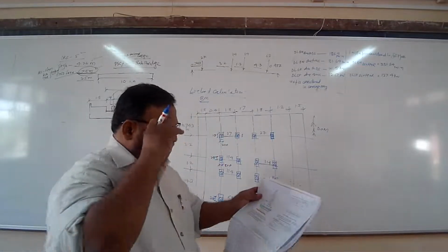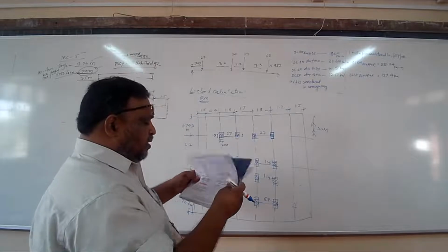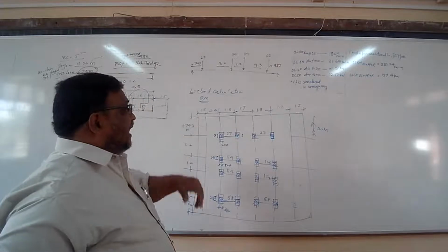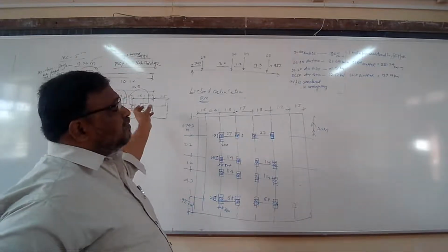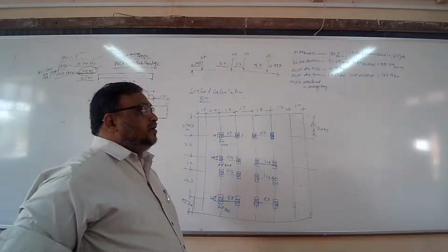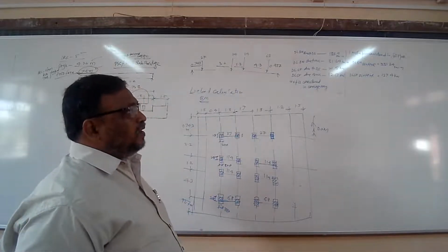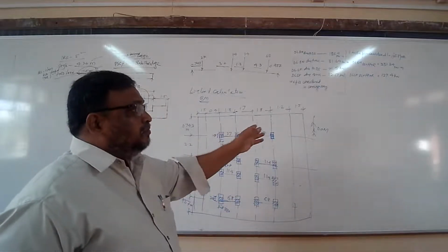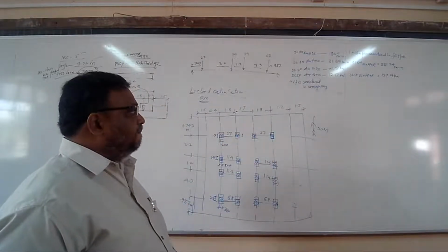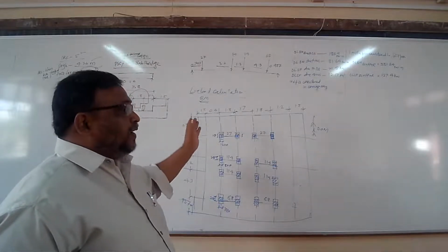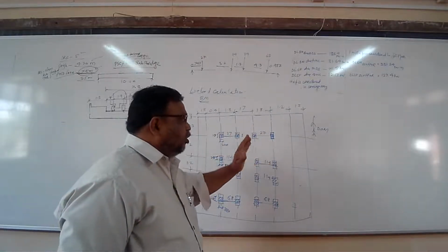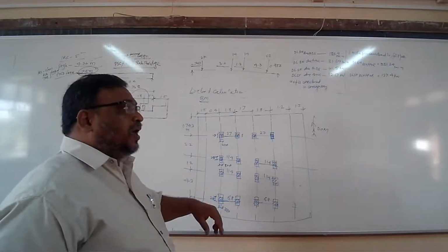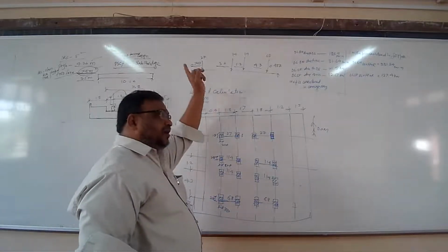ये आपको रेफर करना पड़ेगा पेज नंबर 13 पर IRC क्लास ए। अच्छा, IRC क्लास बी में भी सेम रहता है, सब मैंने पहले बताया है। व्हीकल का डायमेंशन सेम है, ओवरऑल डायमेंशन सेम है, एक्सल टू फर्स्ट टू लास्ट एक्सल डायमेंशन सेम है, डिस्टेंस बिटवीन टू एक्सल भी सेम है। What must be the minimum distance between the two successive vehicles? That is also same, 18.5 meters. सिर्फ चेंज क्या हो रहा है? मैग्नीट्यूड ऑफ फोर्स 27 की जगह पर कितना हो जाता है?